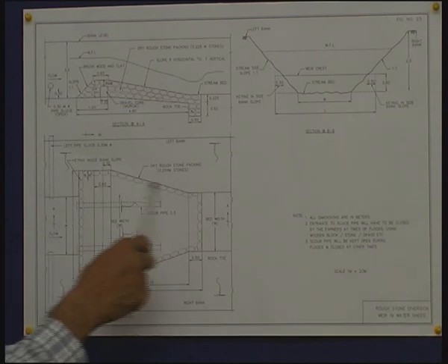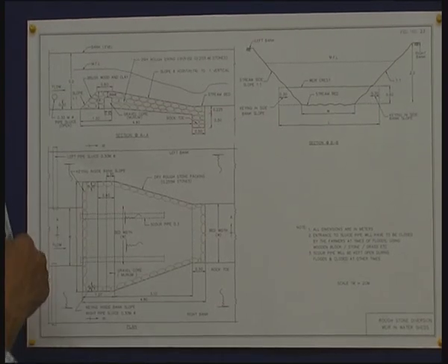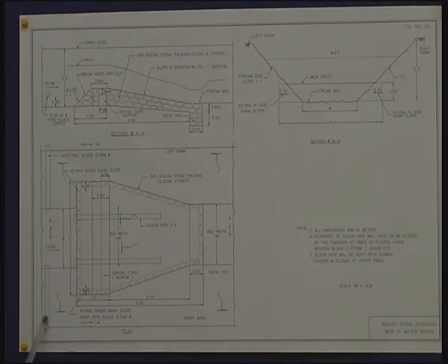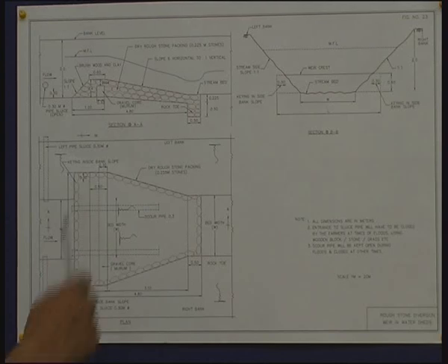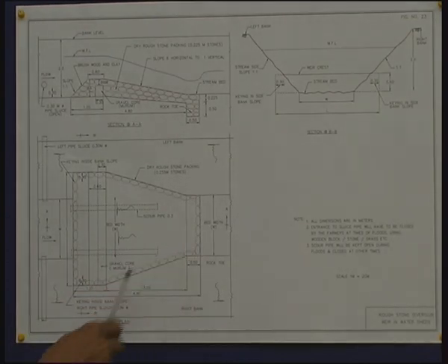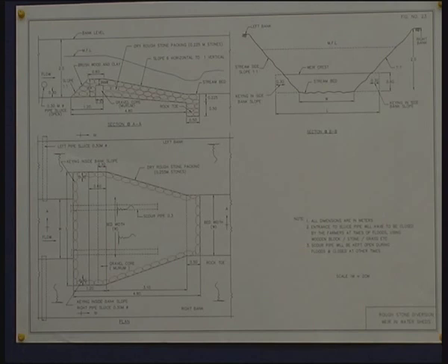When a structure of this type is constructed in the stream, it is possible to divert base flows of 2 cusecs or 3 cusecs into the canal on the right side as well as on the left side. Now, what is the cost of such a structure? This cost is around rupees 4,000, including the cost of the pipes. So, with 4,000 rupees, we can irrigate about 10 or 15 acres on either side, which means about nearly 20 to 30 acres of land we can irrigate through a simple structure of costing about 4,000 rupees.